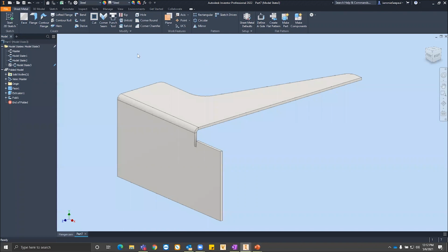But right now, this is just a generic cut, so I'm just going to use a 3D cut. Okay, yeah. Because I know that in the cut tool, there's a special option for cutting around bends, so I can see that being useful. But if it's just a generic cut on a flat profile, extrusion or cut's pretty much the same thing. Exactly. Thank you for that question.